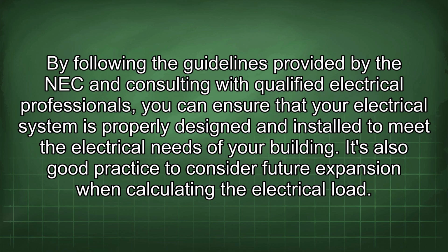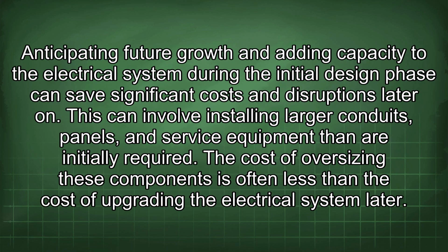It's also good practice to consider future expansion when calculating the electrical load. Anticipating future growth and adding capacity to the electrical system during the initial design phase can save significant costs and disruptions later on. This can involve installing larger conduits, panels, and service equipment than are initially required. The cost of oversizing these components is often less than the cost of upgrading the electrical system later.